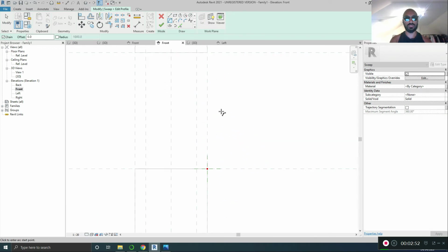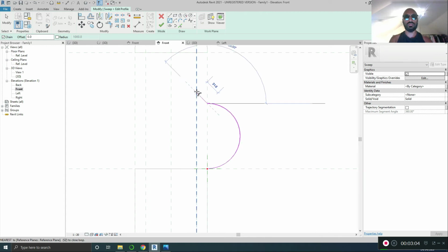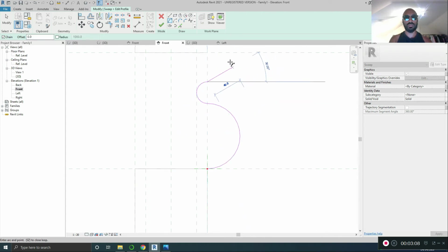Yeah, you select this. The curve by 3 points: start, end, radius. So 1, doesn't matter where. And you snap to the perfect round tangent. Yeah? And then you're going to do one from here to here and snap again. And then, well, it's in chain mode, so I'm going to do the last one here. Snap to the perfectly round thing.